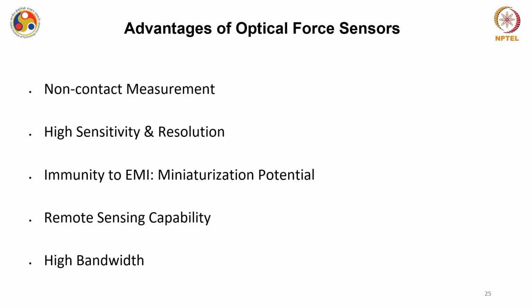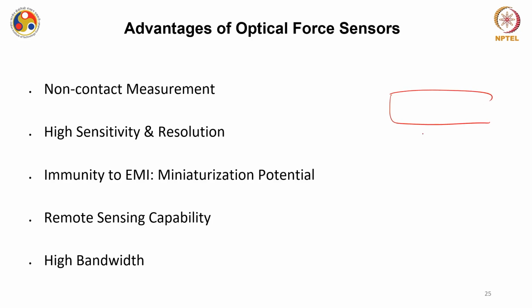The advantage of optical force sensors, the biggest advantage, is that they allow non-contact measurement. Please remember, let us recall the first lecture where we discussed strain gauge based sensors. There you have an object, and you have literally glued strain gauge devices to measure the deformation.